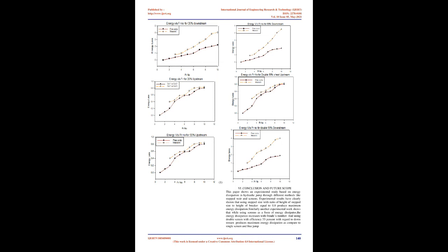Now we go with the step size breaker to form a hydraulic jump in such a manner that the edge of the breaker touches the previous breaker. The height of the breaker changed in the ratio 0.20, 0.40, 0.60, 0.80, 1.0 and thickness is 2.0 mm.